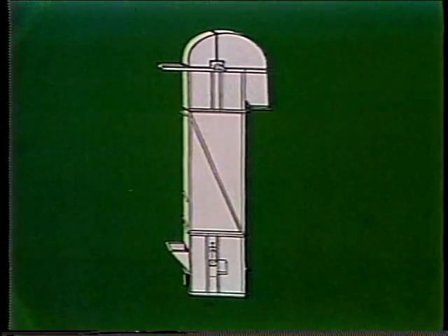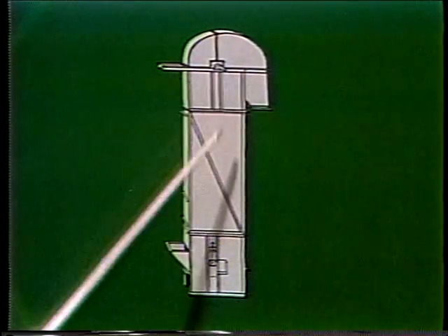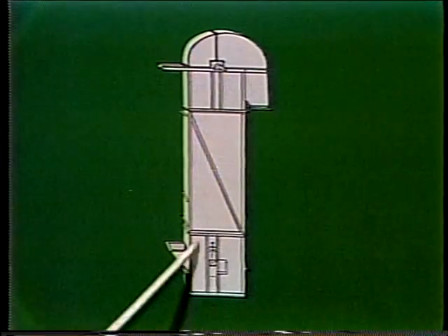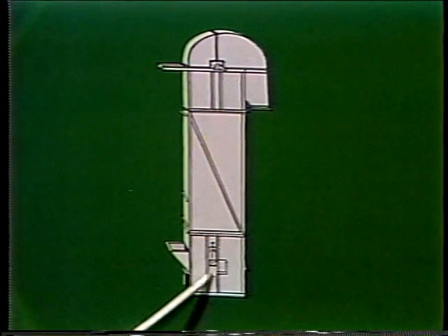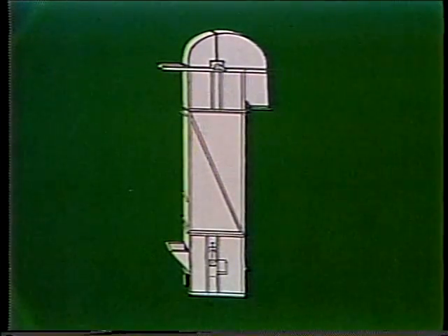On a belt bucket elevator, flat woven belting or sometimes standard transmission belting is used, and in either case we must use a special wide head bolt, simply so the bolt head won't pull through the belting. Each elevator has a head pulley at the top and a tail pulley mounted at the bottom, and a take-up either at the head or tail pulley so the belt may be kept tight.